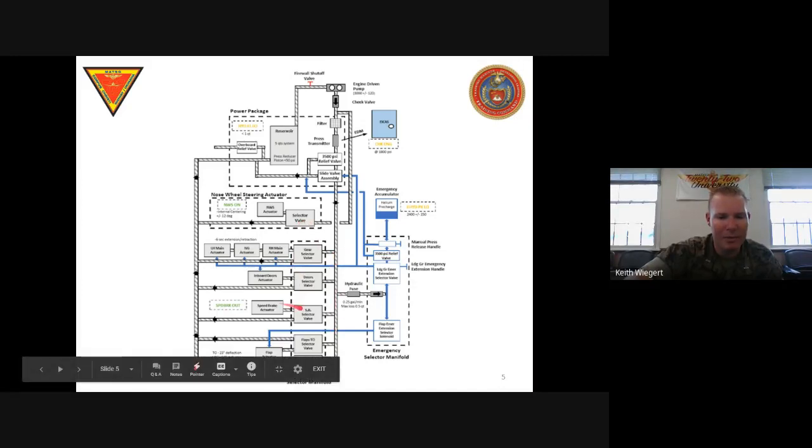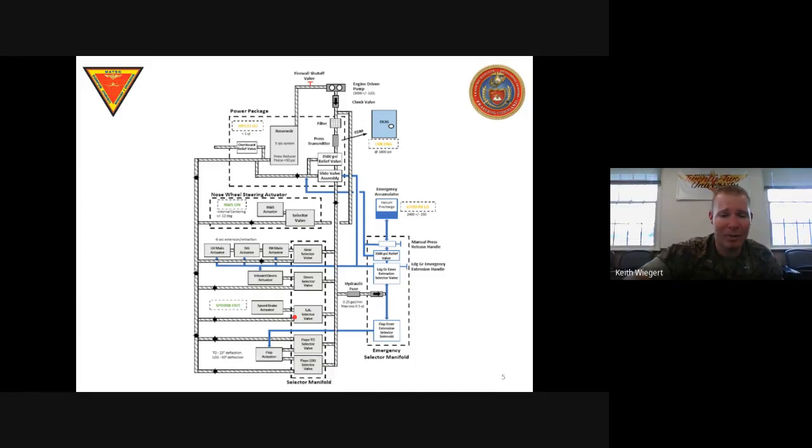Moving on down, the speed brake. So you've got your speed brake selector valve. It's going to be the one that's kind of all on its own over here. When you drop that speed brake, you will get the SPD BRK light out, right? Let you know that your speed brake is actually extended, and you're going to feel it inside the plane, right? It's going to feel like you're driving down a dirt road. That speed brake doesn't have a speed limit. You can use it whenever you need to, right? But I recommend getting it in before you overspeed the aircraft at 316 knots, right?